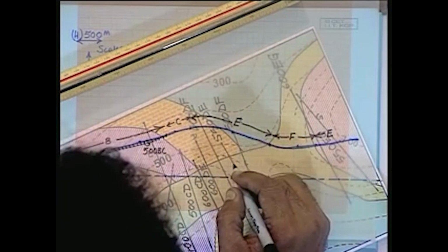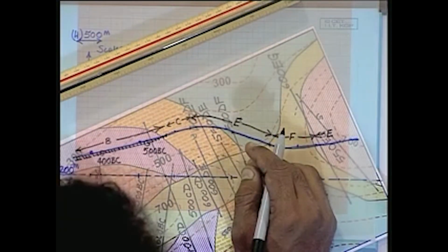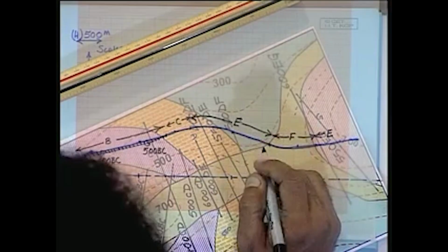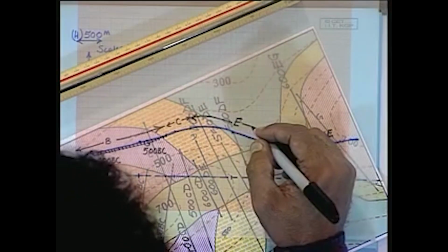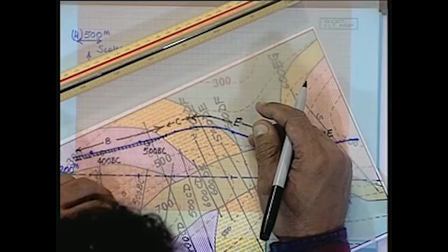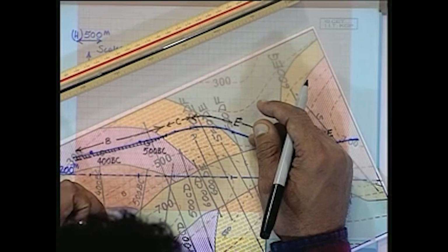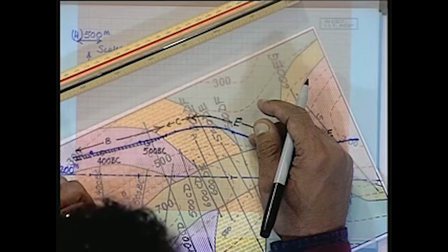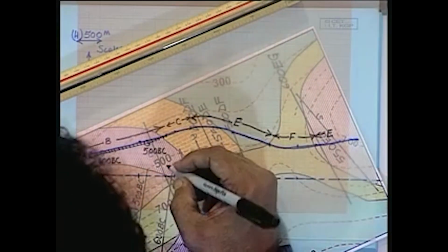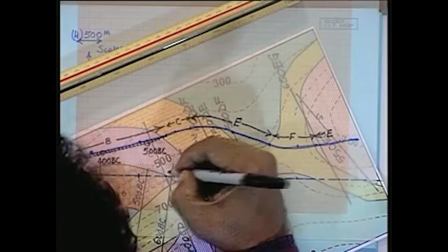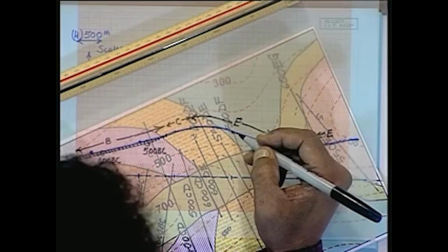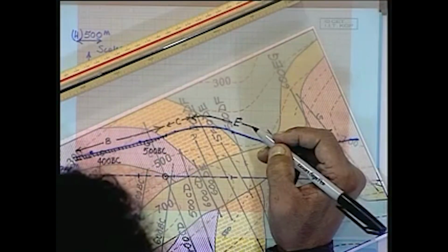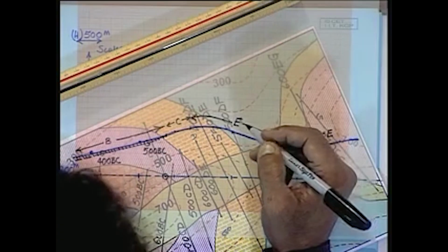So let's now delineate the bottom of unit C. So let's look at the interface between unit C and D. In order to do that, we are going to follow the exact same procedure. Now we are going to project the strike lines that represent the interface between unit C and D upward. So let's start doing that. The first strike line that represents the interface between unit C and D is this one here. That is the intersection between the strike line and the baseline as well as the section line.